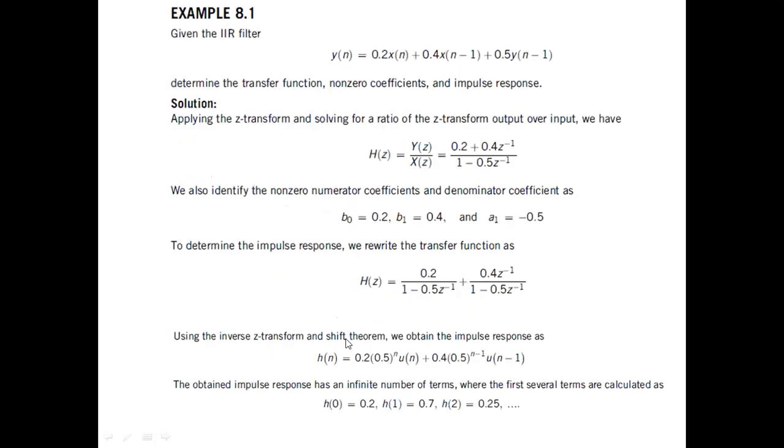So here there is an interesting one given, an IIR filter difference equation. So this is what an IIR filter is all about. Okay, you end up getting a difference equation which contains some values of inputs, present and previous, and the scaling coefficients and previous values of outputs. So whenever somebody asks you to design a filter, we are trying to derive these coefficients, 0.2, 0.4, for whatever the desired frequency response that you want.